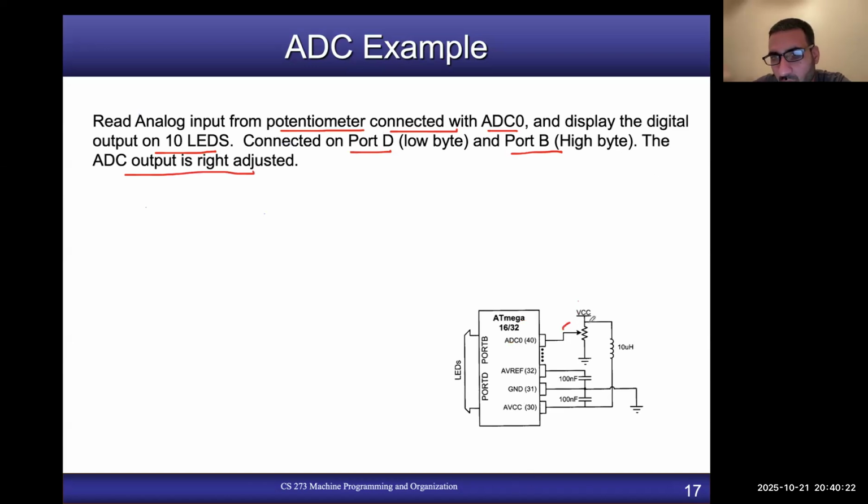So you have this potentiometer here which is connected with ADC 0. It gives you variable voltage. In the lab description I will explain how it works. At least at this point, you don't need to worry about the AVREF voltage. You don't need to make these connections because they are already made for you on your Arduino Uno board.